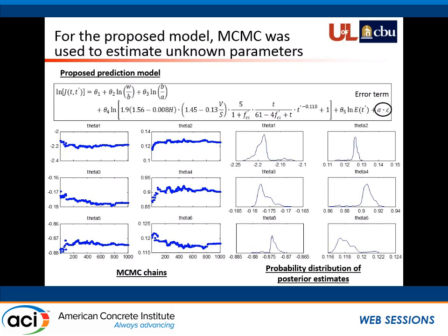We transform the data into log-normal space because the log transformation usually reduces the nonlinearity so that we can easily make a linear model to fit the data points. Because of that, Young's modulus is in another term with another parameter.